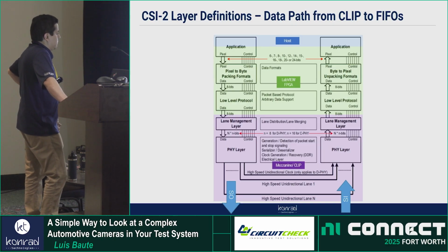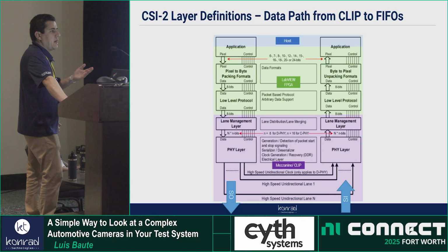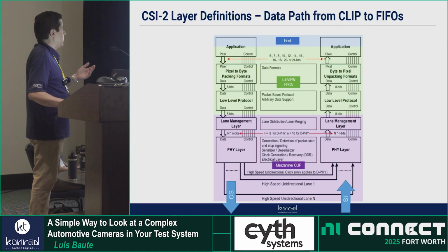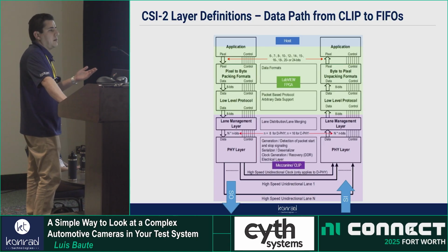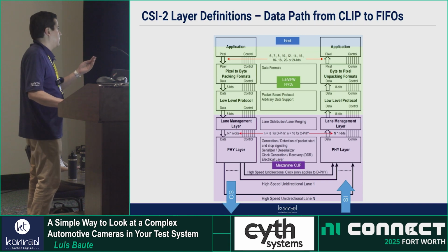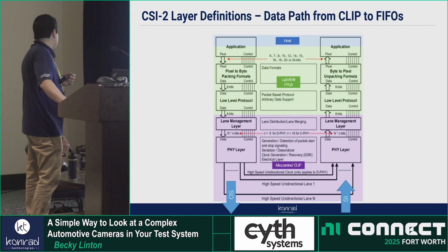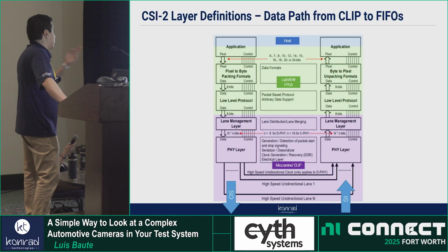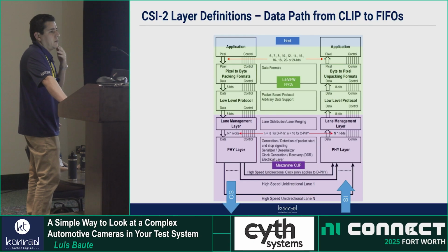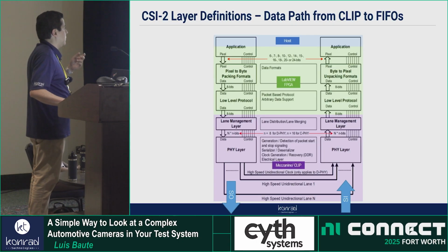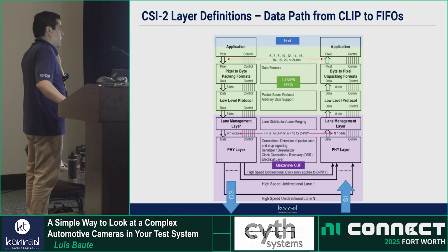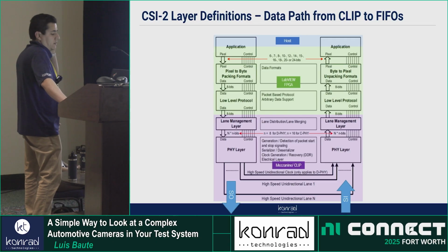And it changes because when you choose, for example, TI, you cannot swap and use GMSL cameras, because TI only does FPD link. And this is embedded with the clip. So this limits also a little bit the flexibility. So you need to decide. You cannot change the camera. Yeah, the purple part we don't touch. That's like the card we pick. Yeah, so that way remains the same because it's always going to be the clip and we don't control this. And then on the FPGA is where we change what we're going to be decoding, and then the host code.